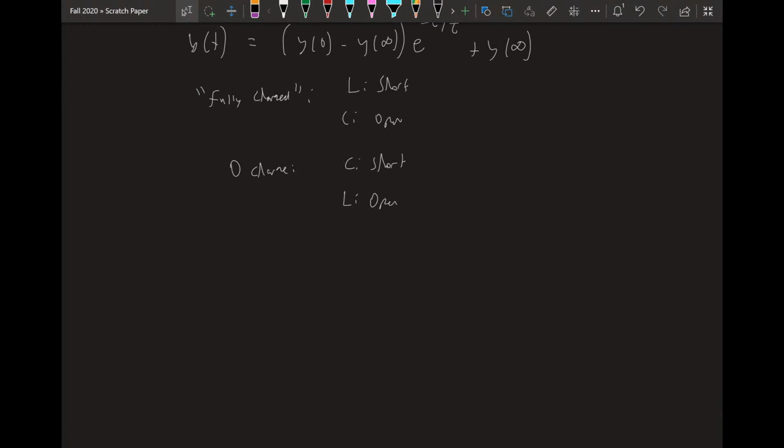So what steps should I use to solve these circuits? Well, step 1: solve for initial conditions. What this means is, solve for the time before 0. Find out what's happening with the circuit before everything starts, before switches start switching and all that stuff happens.